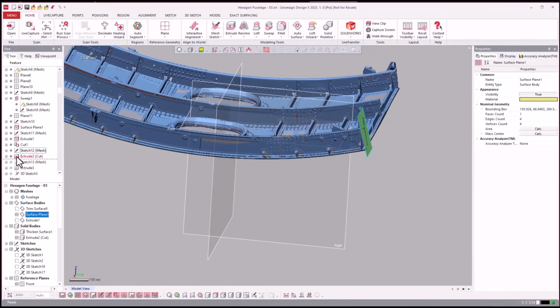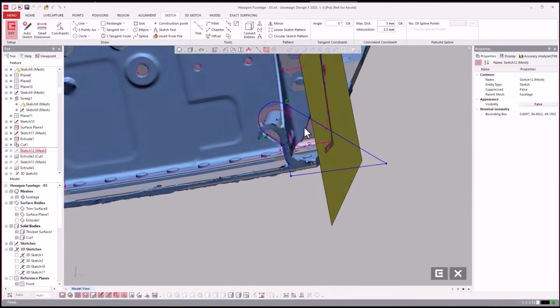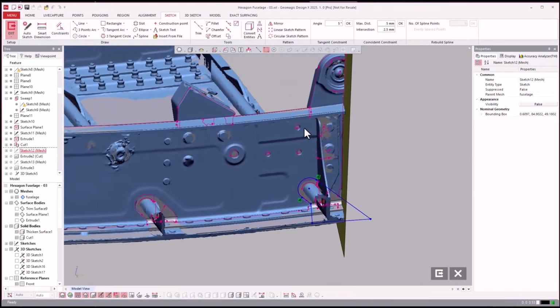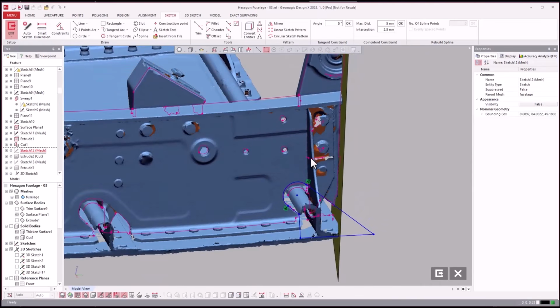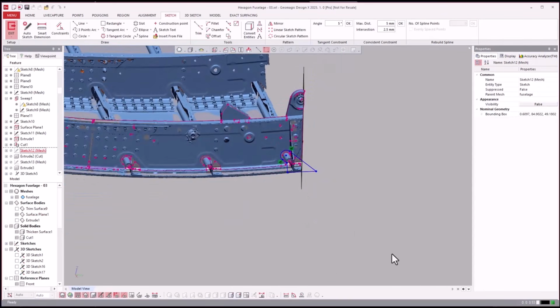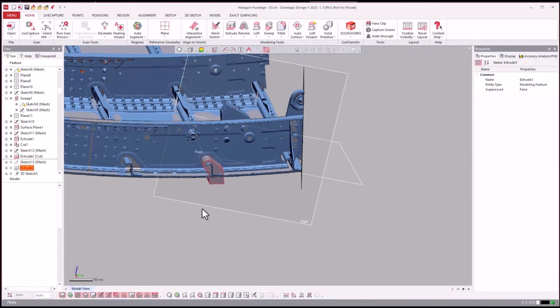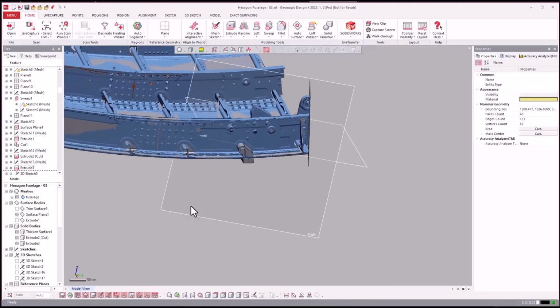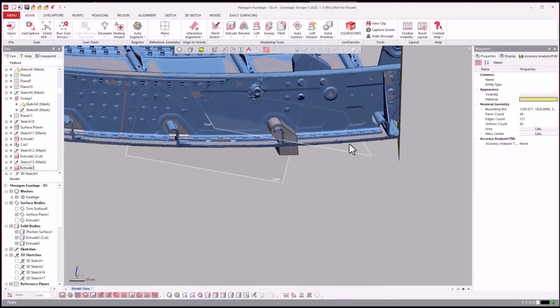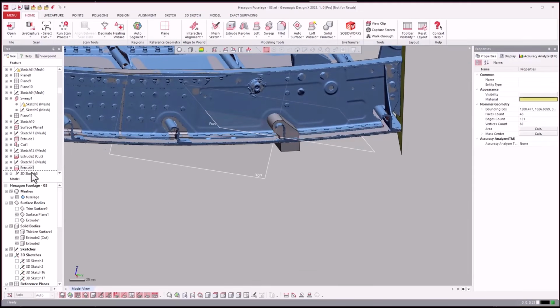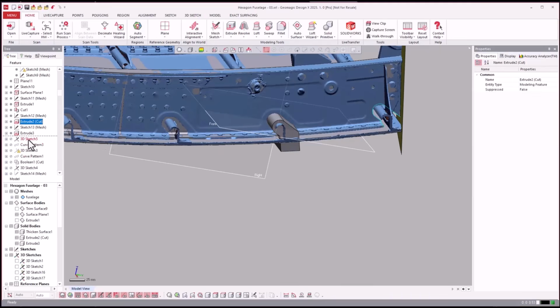Okay, so now we did a mesh sketch for the end here. These beams have hole cutouts, so we drew a hole cutout, and because these were different hole cutouts, we drew another one there.